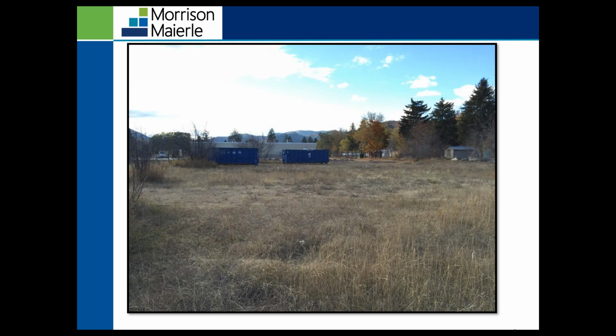This BMP is most effective at controlling erosion and sedimentation at the site perimeter, slopes, toe of slopes, near water and wetlands. It's really the most effective BMP that we can use for preventing pollutants from discharging from the site. You know, keeping those pollutants there at the source, most inexpensive. You know, it's free. It's right there already on the site. So if we can use that natural vegetation for our construction sites, it's really beneficial to prevent sediment from being discharged from the site.